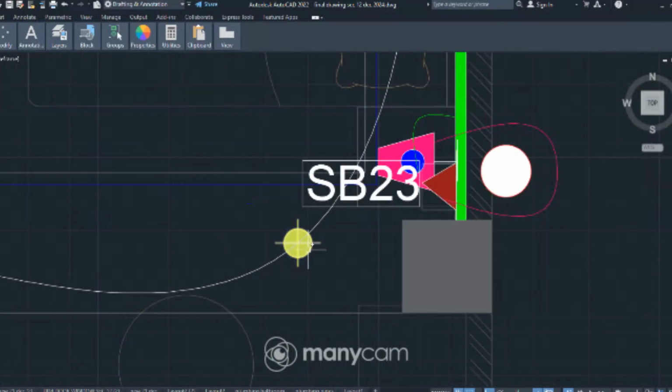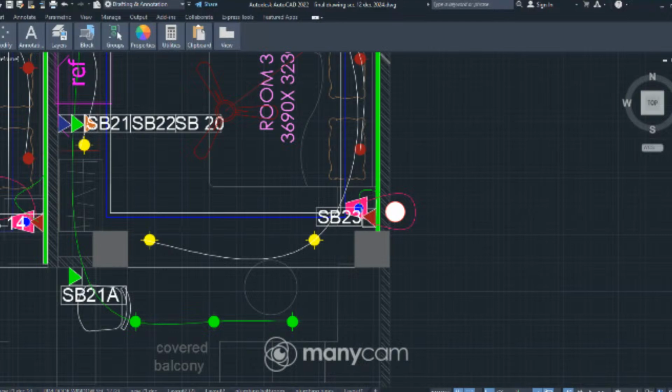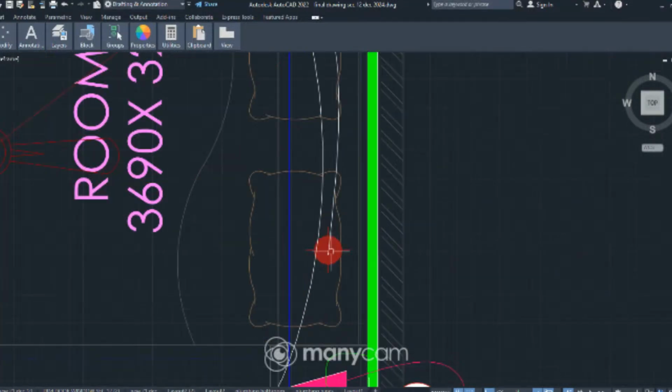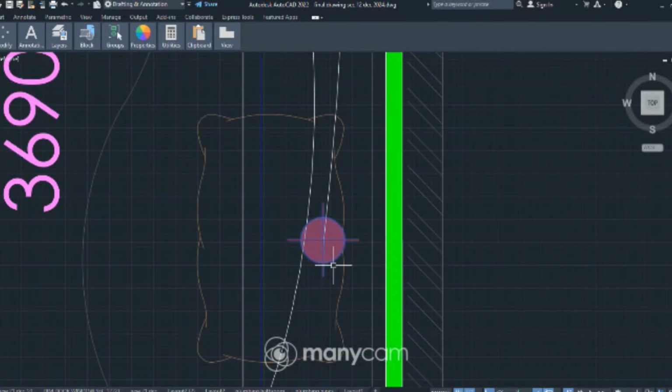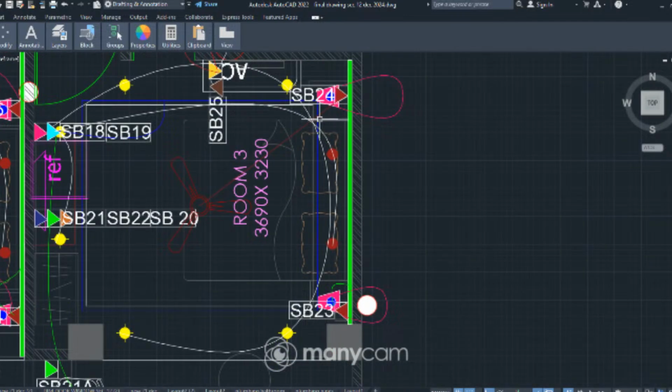So it's easier to put panel lights in places where there are a lot of beams and you're just covering for the sake of the false ceiling and you do not have space in between. There you can plan panel lights, but for others, COB lights look good for sure. They give you that reflection, but only if the space allows. So here we have the place, we are giving it here.